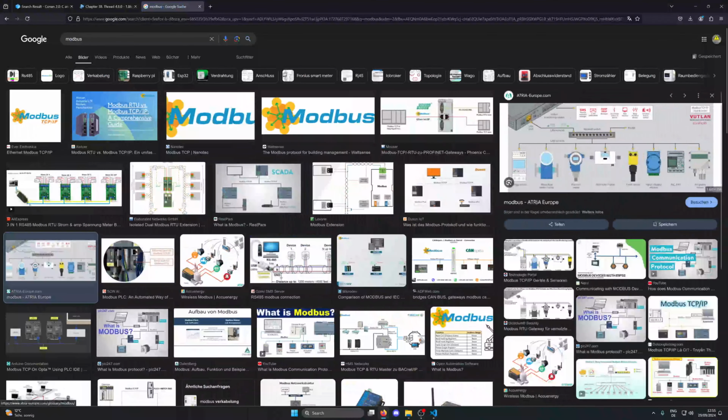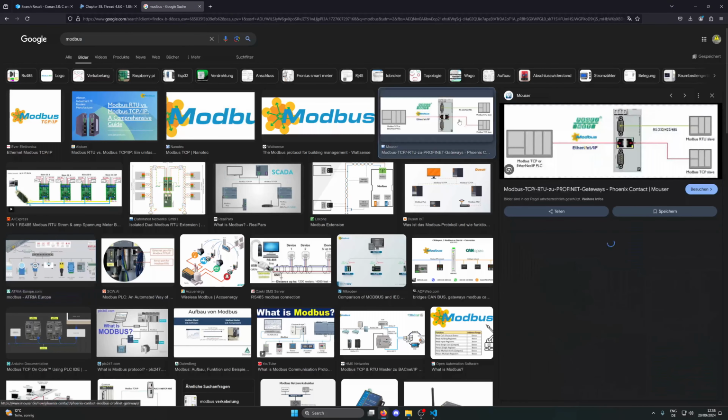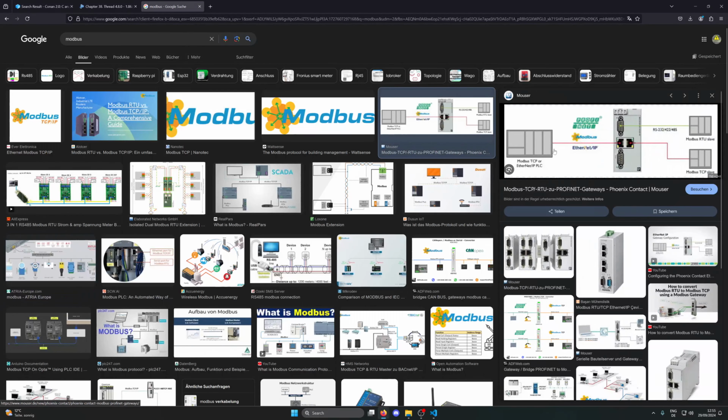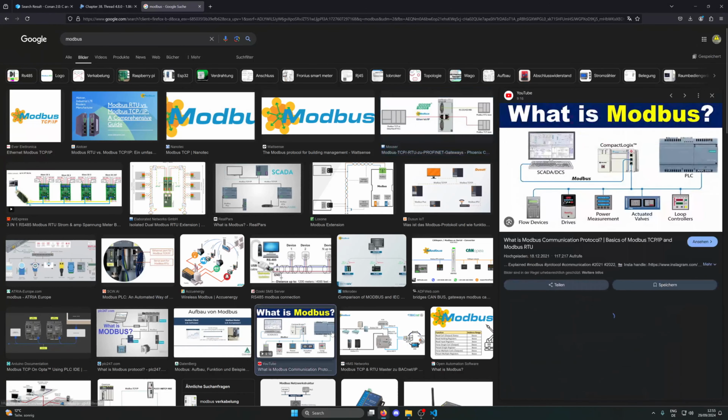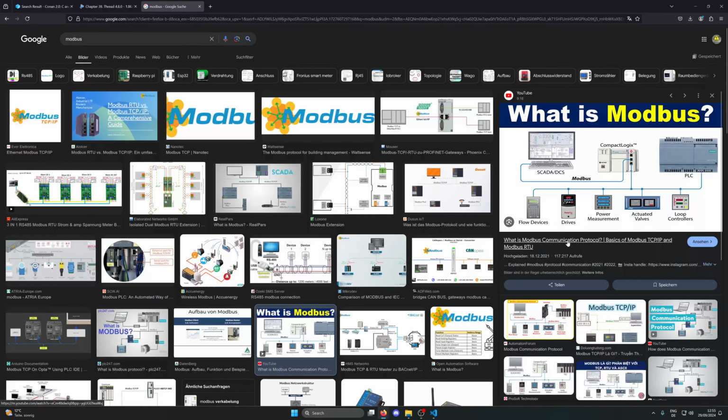If you take a look at Modbus, you can connect it to a PLC, for example, like this Siemens PLC, input-output modules, sensors, meters, and basically it's an Ethernet-based protocol. You have a switch in between, and then you can have some master, some PLC master. In our case, the master will be the computer, and you can control these devices. Actually, with Modbus, you can go quite far. You can even control frequency inverters with Modbus, which is really, really cool.